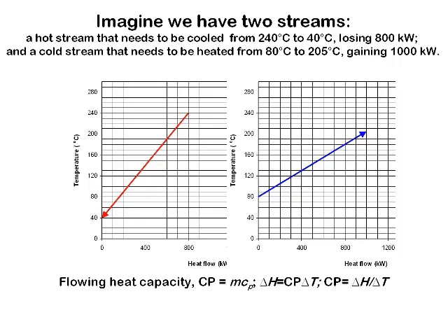Therefore, the relationships between the flowing heat capacity, the heat input, and the temperature rise are shown in these equations. Delta H equals Cp times delta T, so the change in enthalpy is equal to the flowing heat capacity times the change in temperature. The flowing heat capacity is therefore the slope of the graph of delta H versus delta T. So the slope of that graph would be given by delta H divided by delta T. Now our graph is the other way around. We've got temperature on our y-axis, heat flow on our x-axis, and so the slope of our lines is 1 over Cp.